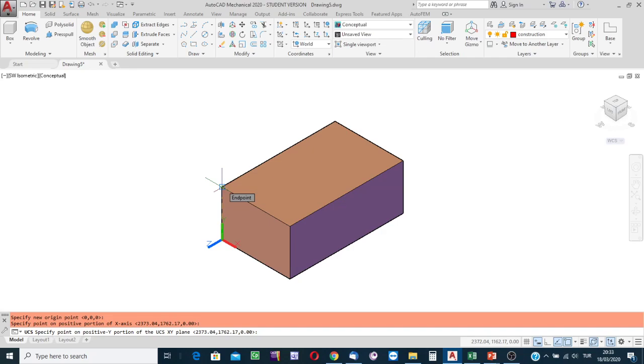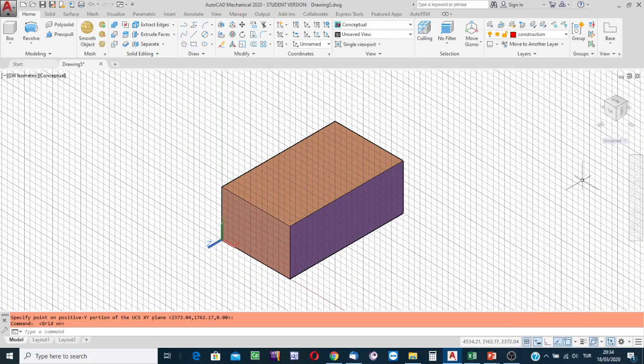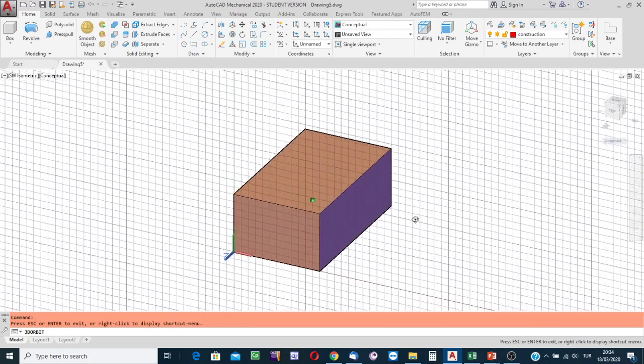It can be indicated thanks to the snap facility, as a point along which the y-axis passes to its positive side. Okay, and then I'm sure that the XY plane is now coinciding with that surface. To see that it is true, click on the grid button to show the grid lines, and then rotate.